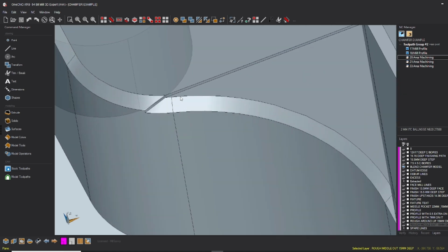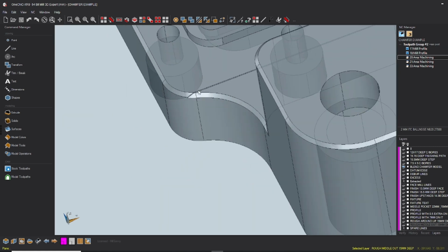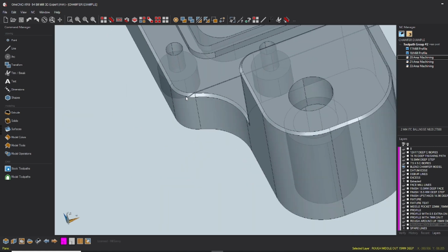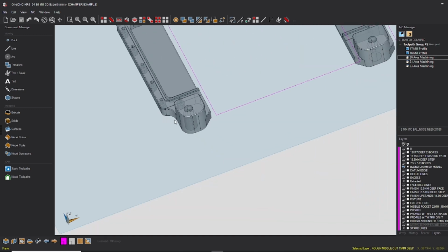For instance, say I was deburring this edge here, and I was laying off this face by 0.1 to deburr it. Then they're not going to be able to drop that spot drill or chamfer mill, whatever you're using to do this edge here, because you're going to gouge into here. But if you use compensation, you can just take a little bit off your radius, or if you're using diameter as your offset, take a little bit off that, and it will move that way rather than this way. And that's why I do it for examples like that, where you're already right close to the edge and you can't really afford to drop that tool.